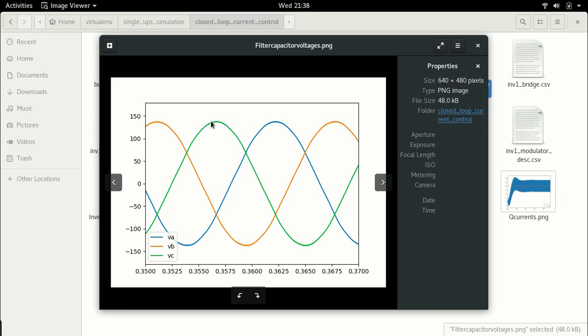The regulated value is somewhere up here. Alright, the reason is simple. We have given some arbitrary currents. We have not given a calculated current. This time we have calculated the modulation index, or rather we have controlled the modulation index to produce a certain desired inverter current. But still there is no control over the voltage. Alright, the voltage is free.